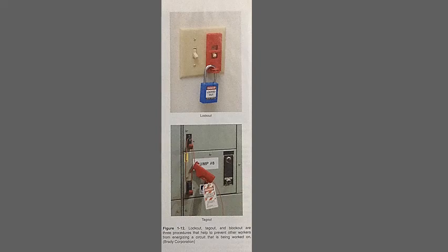After the electricity has been removed and safely controlled, begin talking to the victim in a loud and clear voice. You want to see if the victim is conscious. If there is no response, try to keep the victim still while checking for signs of breathing. If the victim is not breathing, get someone who is trained to initiate CPR or perform it yourself if you are trained. Try to stay with the victim throughout the entire rescue and let the medical team take over when they arrive.